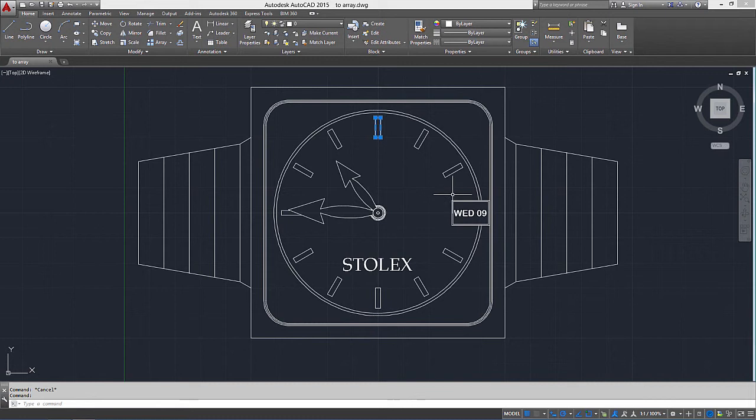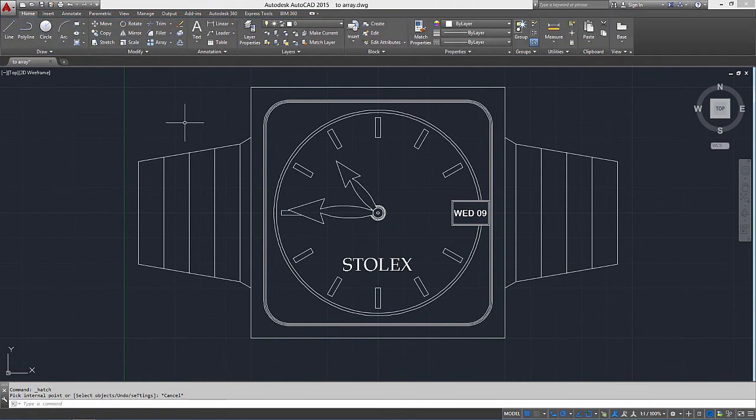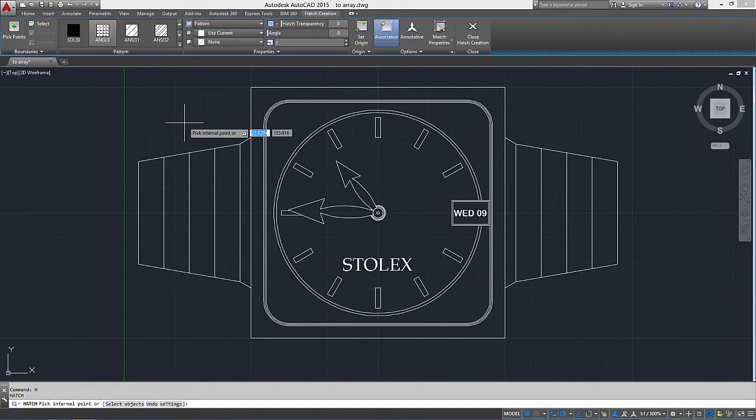And there's a couple of ways of getting the hatch dialog box up. It's a context ribbon, really. So there's this one, hatch. That will do it, and you get this hatch creation ribbon as opposed to the hatch editor ribbon, which is nearly the same but not quite. Alternatively, you can type in H on the keyboard and that will get you to the same place.